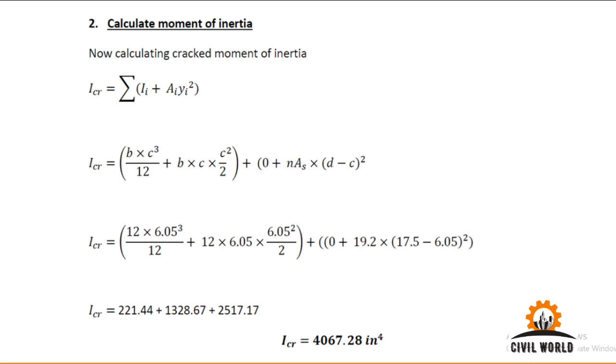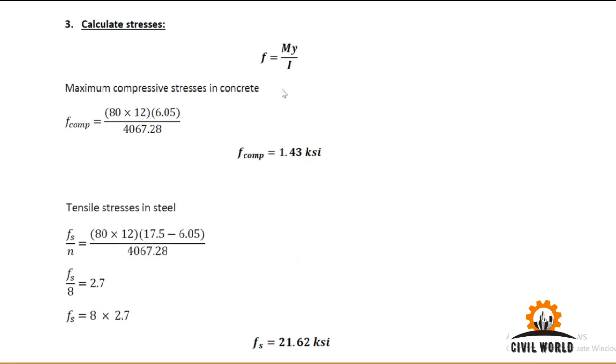4067.28 inch raised to power 4. So now you have the value of I. You can calculate the value at any point from the neutral axis, y. You have the applied moment, and you can use this equation to calculate stresses in concrete and stresses in steel.